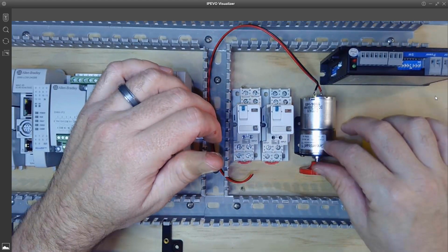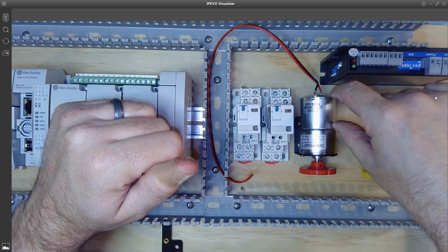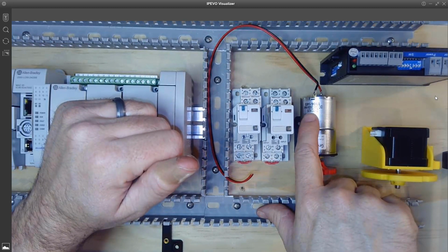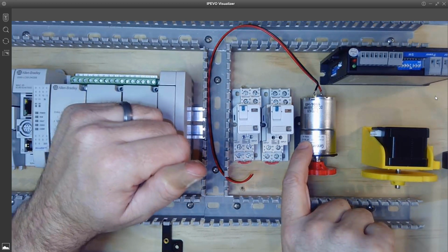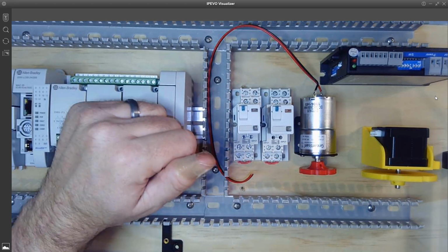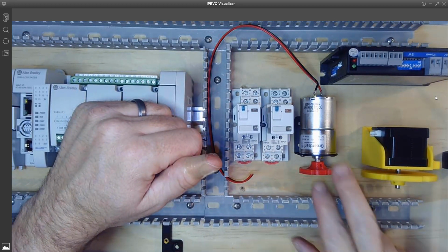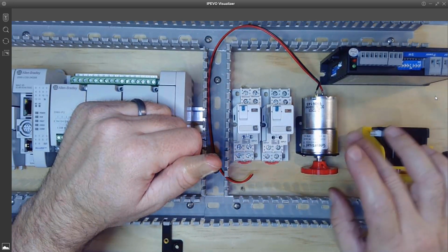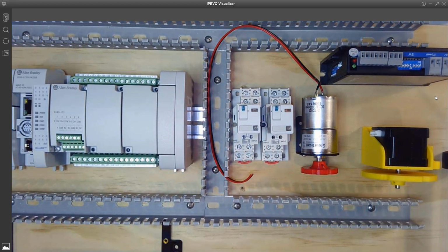And then the last thing we'll talk about today is this little DC motor. It's a 24 volt DC motor, and so this is the motor part right up in here, and it has a gear head on it. So if you look at the label here, it says the motor itself is 3,500 RPM, but then once the gearbox reduces that down, we're at an 85 RPM. So it's a nice kind of safe, slow speed with a fair amount of torque though from all that gear reduction. So one of your tasks this week is going to be researching and coming up with a schematic for how to reverse a DC motor using a relay. Okay, I think that's enough of an overview of the components we'll be using this week.